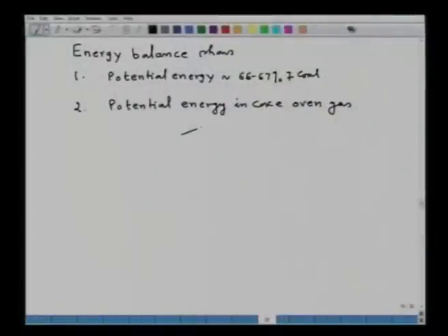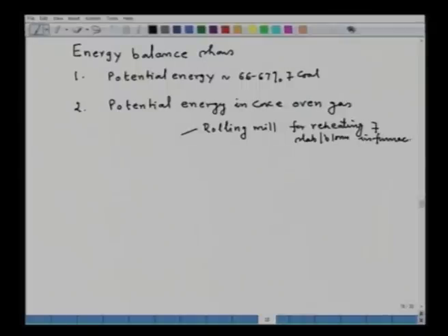So here itself one should think that this calorific value can be used, say, in rolling mill, say for furnace reheating, for reheating of slab, bloom in furnaces, because in thermomechanical processing the slab, billet or bloom are heated to a high temperature and then they are being rolled. So in that, coke oven gas can be considered for its potential application.